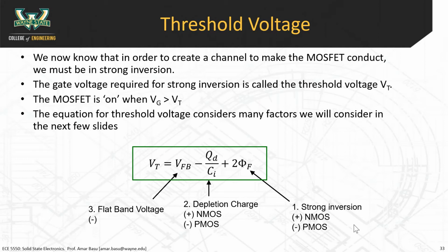Second thing is, it turns out that when you're dealing with large threshold voltages, your MOSFETs require more power. Right. So there's an incentive to actually use lower threshold voltages. Okay, that's a second practical issue. Some of you may have seen some of the MOSFET devices that are used in the Intel Atom processors, the mobile processors. Those are low voltage transistors. Sometimes they work at around 1 volt, a little bit above. Some of them work below 1 volt. So low voltages can save power.